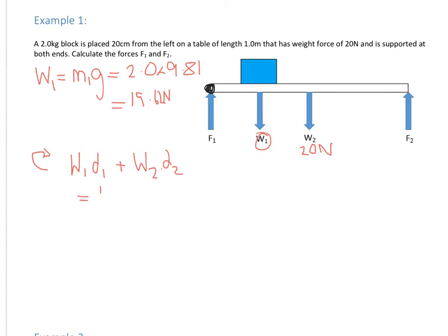So that's going to be this 19.62 times 0.2, because that's the distance of that from the pivot, and then 20 times 0.5, because the weight force of an object acts from its geometrical centre. So if that's 1, that's going to be 0.5. If we calculate that, let's just type that in: 19.62 times 0.2 plus 20 times 0.5. So we end up with 13.924...